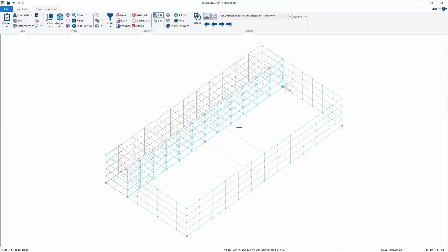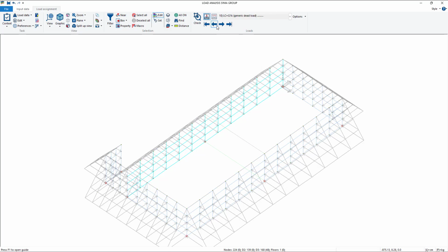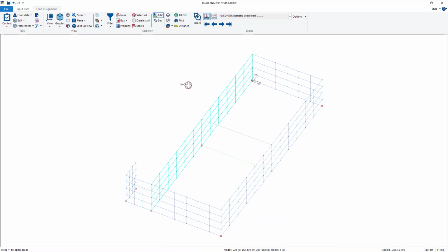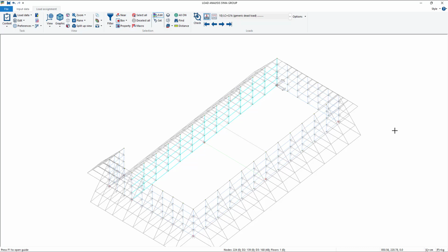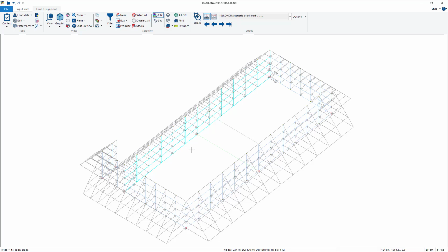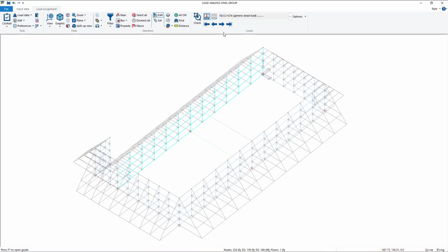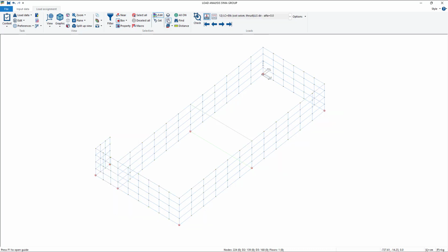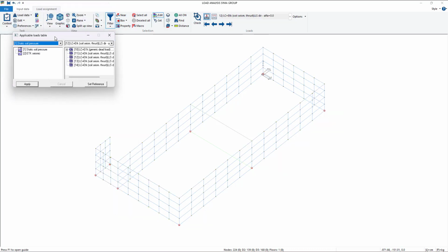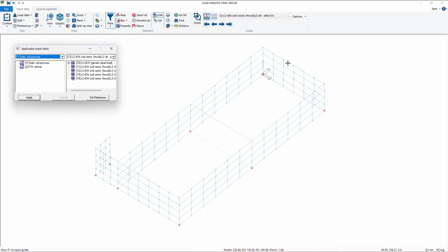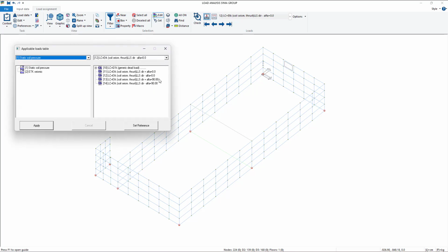And now basically we do the same for each other region. Let's see, okay, we don't have to disturb the other static load. So well, sometimes just check also other loads. And okay, now we can move on to the other walls. Click here. We have to apply the load in the negative direction of the y axis. So direction 90, sorry, negative. So the load is always the same, negative direction, apply, set reference.